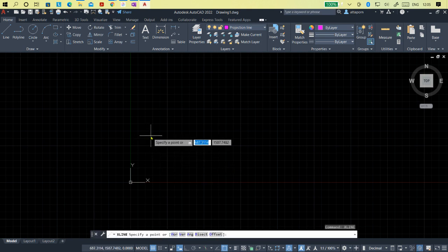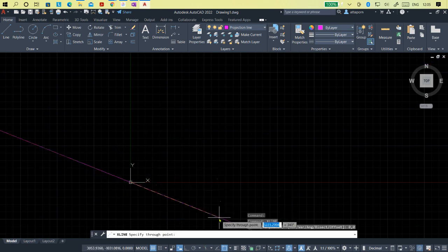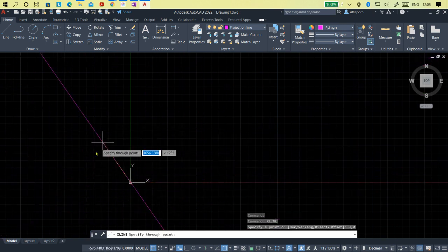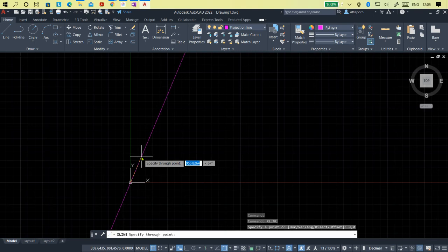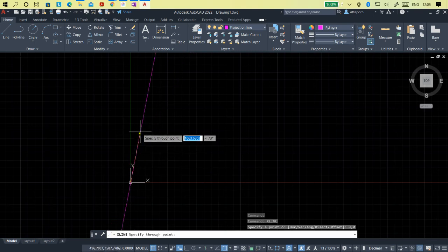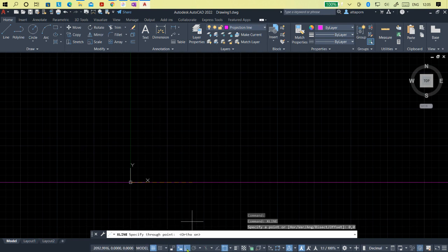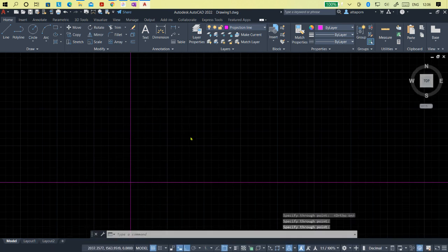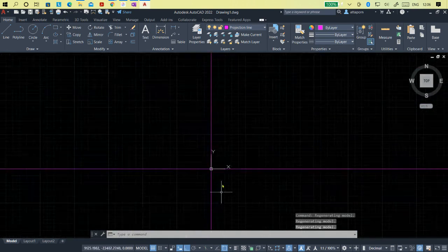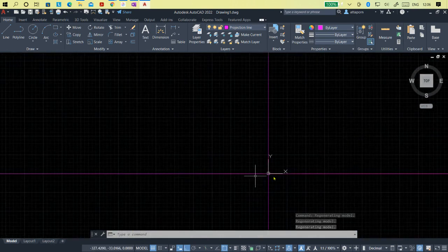So specify a first point. I often start at 0 and 0. Okay, 0, tab, 0 and enter. Now it's not fixed at an angle, right? For the projection line, you know that we just draw vertical and horizontal, so I recommend you turn on this ortho mode. Okay, on. So make vertical and horizontal first and enter. Okay, just two lines. You see that there is no end and no starting point of these lines.